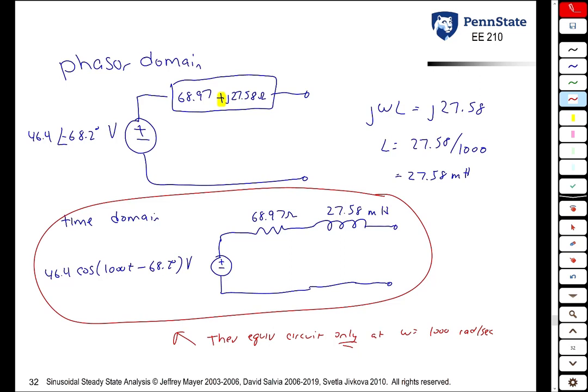So we've done a number of examples here. We used Thevenin's theorem, we did mesh analysis, we did current division, we did voltage division, we did a source transformation, and what we're seeing is all of these different circuit analysis techniques that we used earlier, we can use again now in sinusoidal steady state analysis. The only wrinkle is that we have complex numbers, so it's important that you're adept at using complex numbers on your calculator so that you can do these calculations relatively quickly.